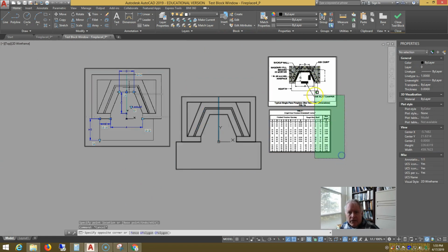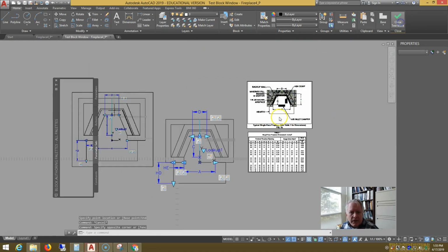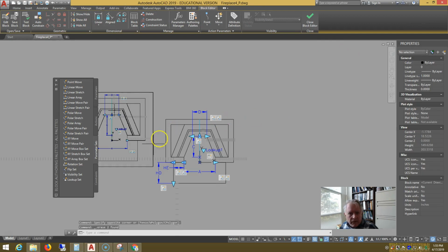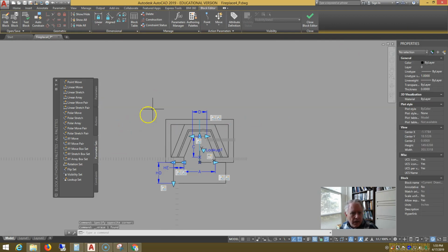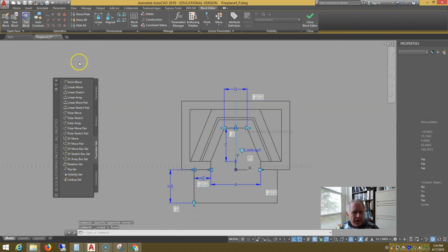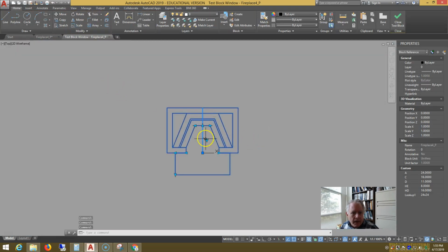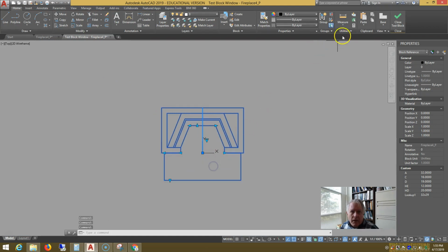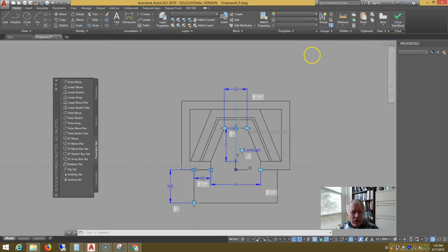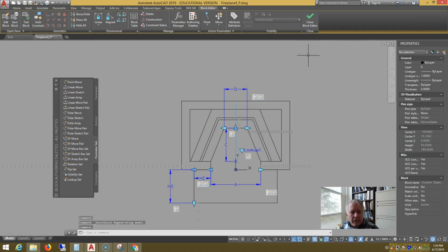Ultimately, at this point, let's go ahead and close the test block, get rid of the images, test it again without the images, and it should work. And you may want to add the hatch. This space here and this space here is for grout, if you want to hatch grout. But the hatch will work if the hatch is associative without including it in the selection set.